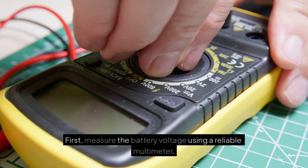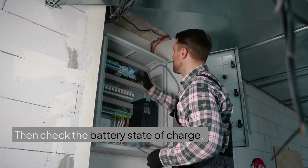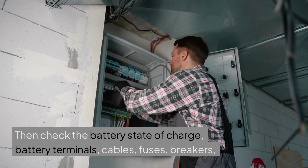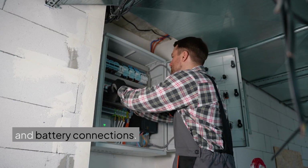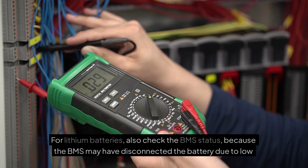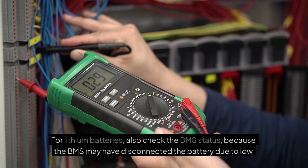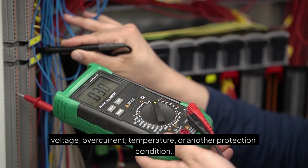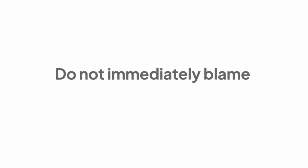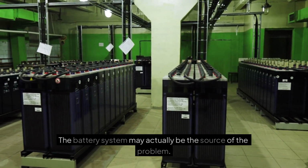First, measure the battery voltage using a reliable multimeter. Then check the battery state of charge, battery terminals, cables, fuses, breakers, and battery connections. For lithium batteries, also check the BMS status, because the BMS may have disconnected the battery due to low voltage, overcurrent, temperature, or another protection condition. Do not immediately blame the inverter. The battery system may actually be the source of the problem.